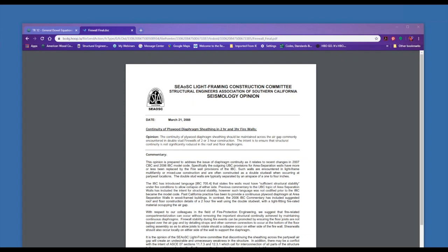While carriage bolts are kind of a weird thing, they are not included when we talk about bolts in the NDS. We talk about bolts manufactured in accordance with, I believe it's ASME B18.1.2. Don't quote me exactly on that number, but there's an ASME standard for the bolts that are included in the NDS, and carriage bolts are not included in that.